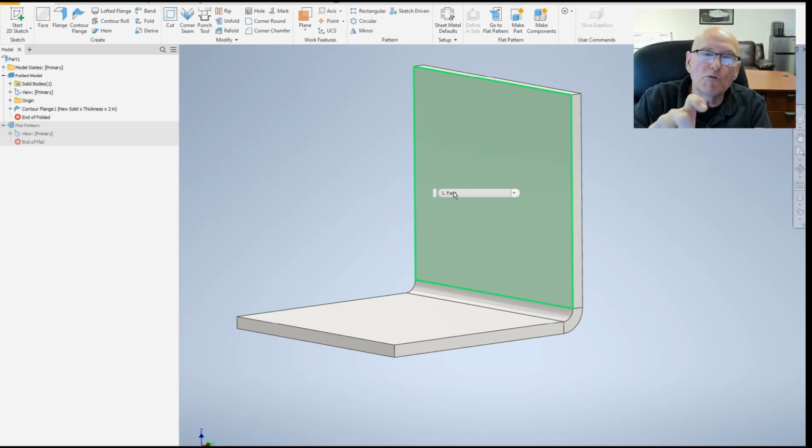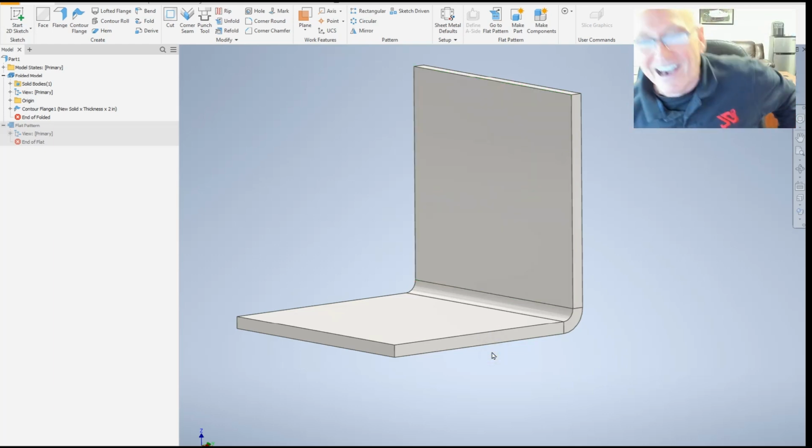We're going to measure both legs, take that difference, and apply it. We're going to make changes to our K-factor until the new billet, instead of being 4 inches, is that length that we have calculated we need. So let's go through that process real quick, because I don't know if I explained that clearly enough.